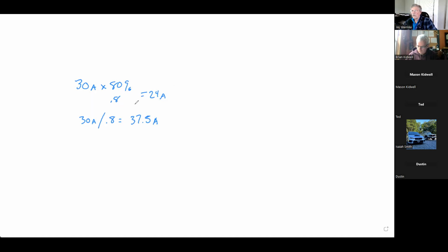Okay. And so you run into this a lot. Let's say we're derating our system, and this is in a future chapter, that our system that we've configured will generate 3,500 watts. But it's only 90% efficient. So if I derate this and I say, okay, times 0.9, then 3,500 times 0.9 is going to get me 3,150.